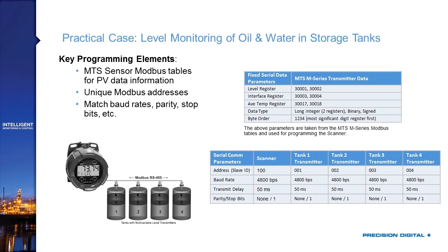There's this thing called transmit delay, which is specified. And that's a great example of one of those values where, well, not really sure what that is, so why don't we just leave that one alone? Most likely it's shipping from the factory in such a configuration that I only need to mess with it if I have a problem. So I'm going to skip over transmit delay. It's currently 50 milliseconds. Sounds good to me. The system will work fine with that.